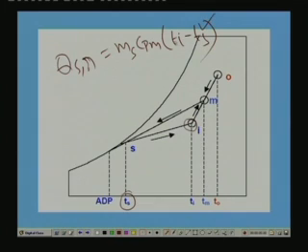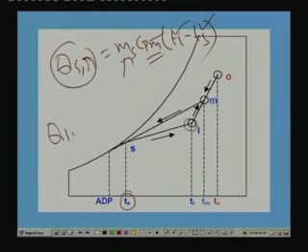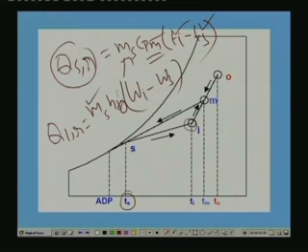So, Ts is specified, Ti is known to us, Cpm is known to us. So, you can find out what is Ms. Similarly, we have seen the other equation, the latent heat load, which is Ms times Hfg into (Wi minus Ws). So, Ms is calculated, Hfg is known to us, Wi is known to us, so Ws can be obtained. So, you can fix this condition also.